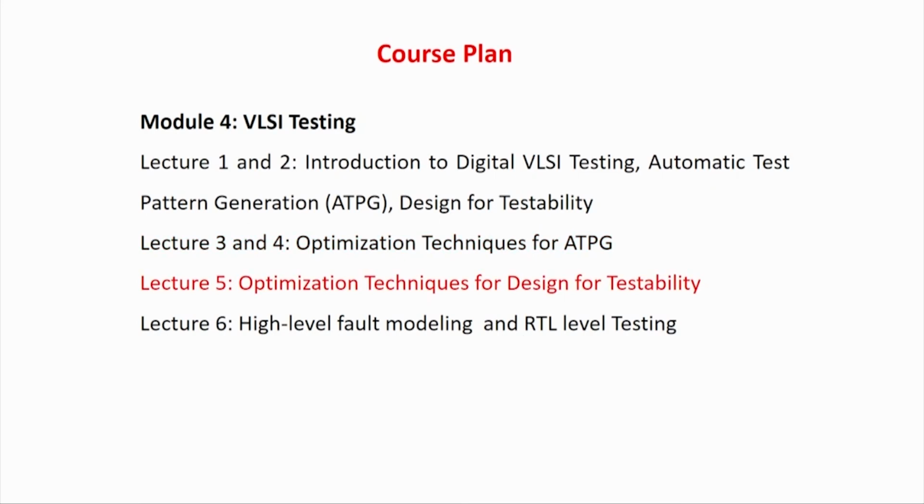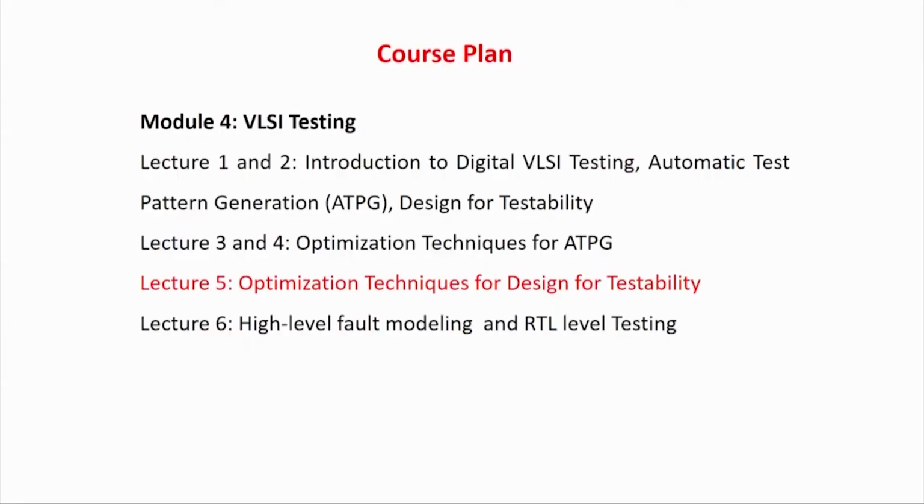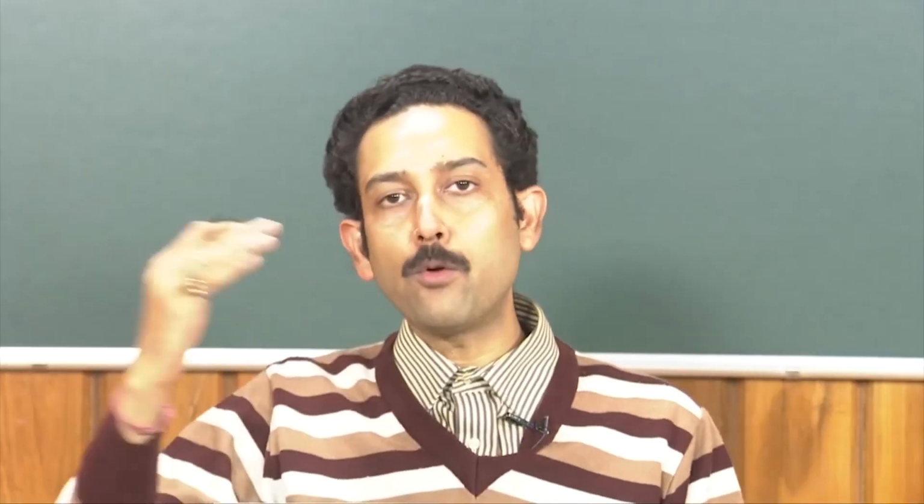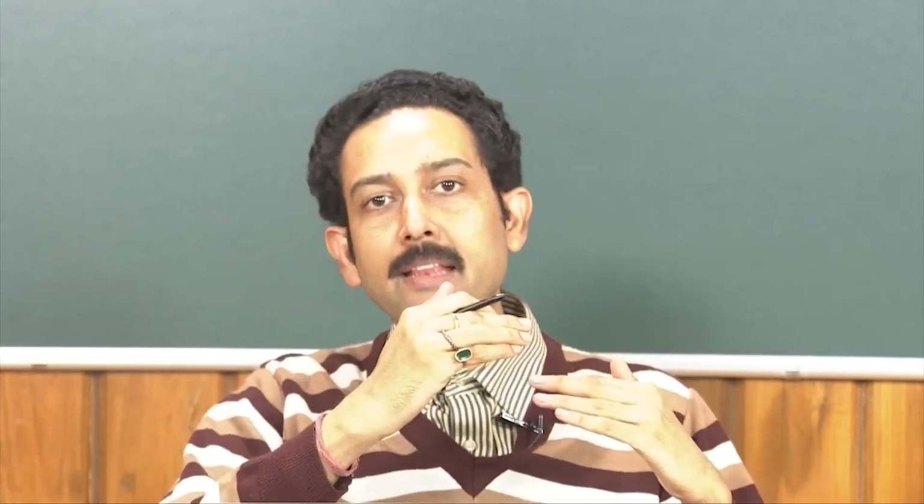Throughout this module on VLSI testing, you might have observed that we first discussed what the different ways to generate test patterns are. That is the basic idea of testing digital circuits, and then we tried to optimize it so that we can handle larger circuits. When we talked about scan chains, or when we put a compaction circuit while optimizing ATPGs, we were optimizing the test patterns that are generated. So we merge or compress them, and we use compaction techniques for the output generation, so that the number of pins required for the ATE is reduced and so forth. Different techniques were used so that we can handle large circuits and do efficient testing on them.